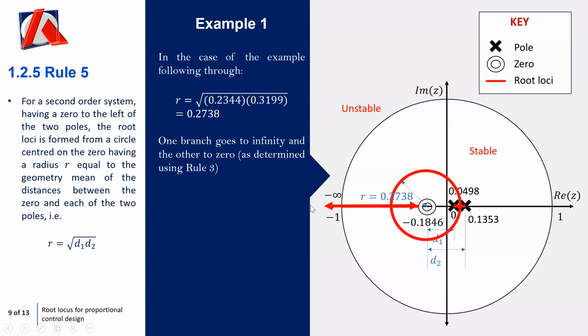And this is what's happening when you increase the proportional control gain on the feedback control system. With root loci, we just use the open loop transfer function, but it's assuming that we've got negative unity feedback and proportional control gain in the feed forward path. And that is the path of what's going to happen in terms of your system performance. So as you increase that proportional control gain from Kp equals 0 to a given value here, you know that your system performance is going to change.